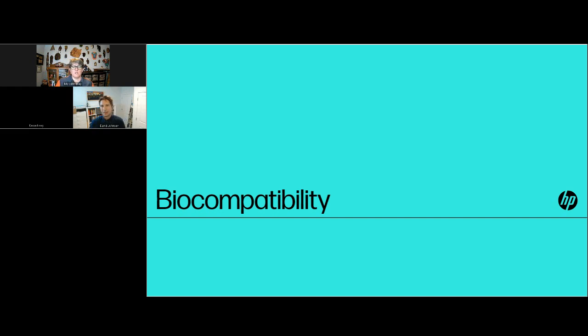I was a manufacturing engineering rep on multiple design teams, and as part of project kickoff we would evaluate the processing steps, what kind of cleaning, and those types of things. This really needs to be considered at the initial project creation step. When you're developing the manufacturing processes, they need to either be identical to a previously cleared device, or have passivation at the end, or you need to budget a lot of time and money for actual testing or further justifications, which have had some success here and there. So it's definitely something to do on the front end. The full battery of testing will take 6 months and cost $300,000 in a semi-worst case.